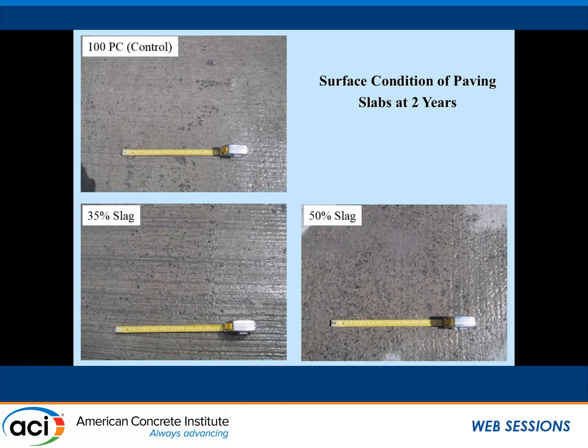But in the field, we are seeing a little bit of maybe some coarse aggregates being exposed, but in general, the field performance is not really mirroring what we're seeing in the lab at all. I think Jan made the point, somebody else made the point before this week. The de-icing salt scaling test is really very, very severe, especially for concrete that contains blended cement. And especially if you follow the curing procedure, which is 14 days wet curing, followed by 14 days drying. With that surface strength after 14 days wet curing, you're not going to get anywhere near equivalent performance when you have 50% slag in there. So it's a very aggressive test.